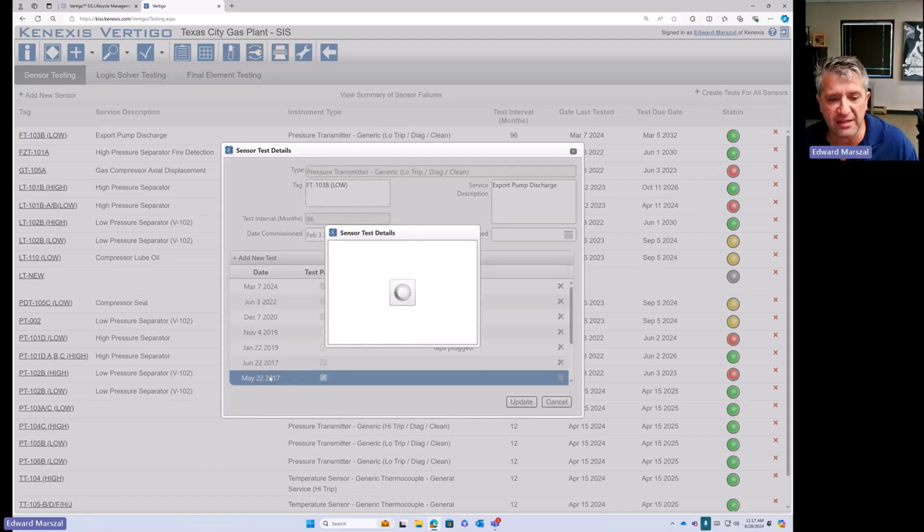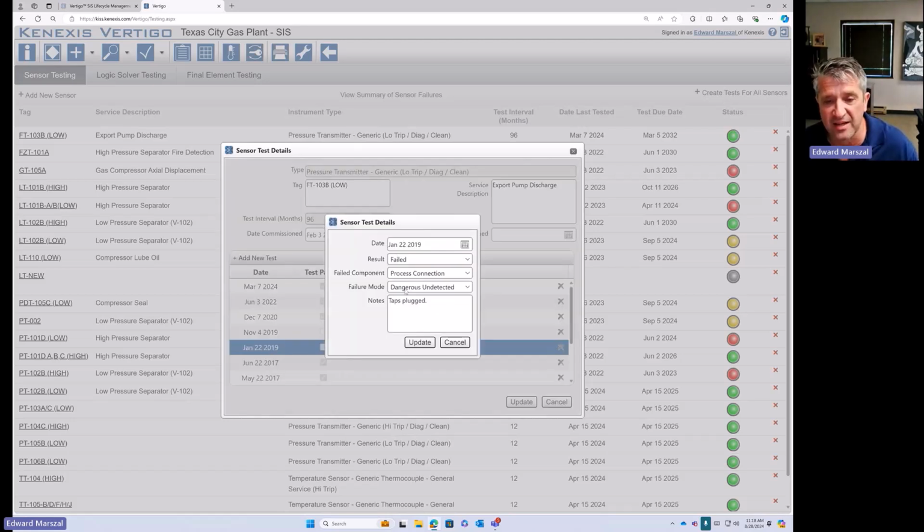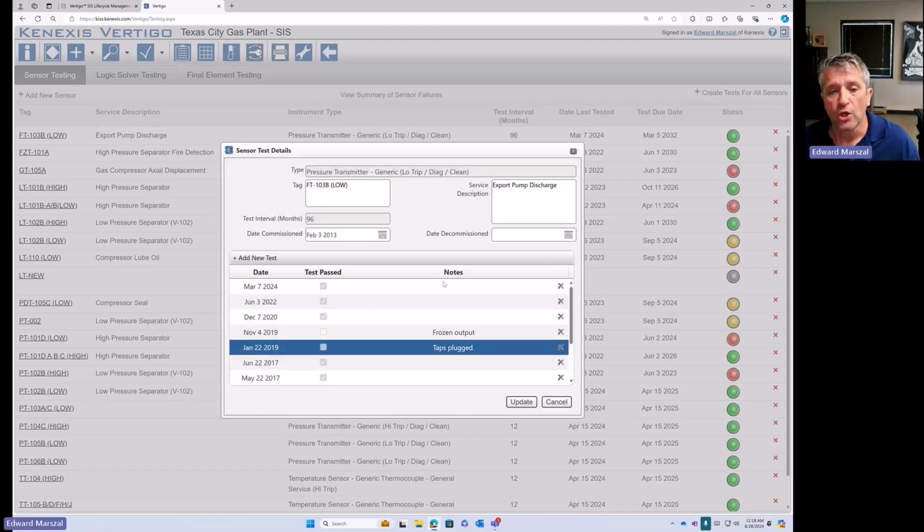So on May 22nd, 2017, I had a test and it passed. On January 22nd, 2019, I did a test. It failed, dangerous undetected, and the mode of failure was that the taps were plugged. So you can track all of this information yourself. You've got the red light, green light, yellow light to tell you whether the test is 6 months or more in the future. Yellow means within the next 6 months. Red means you're past due. Gray means I don't need to test this for whatever reason. It's not installed, what have you, taken out of service.